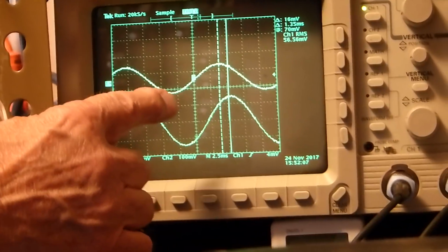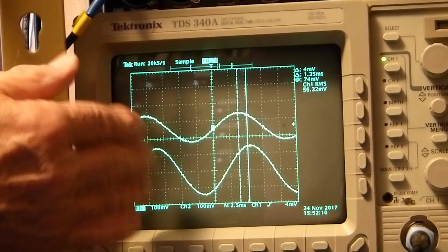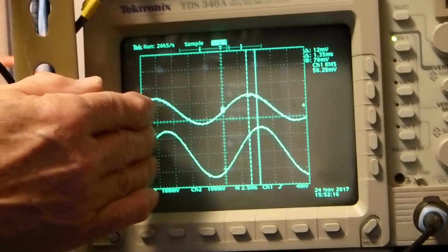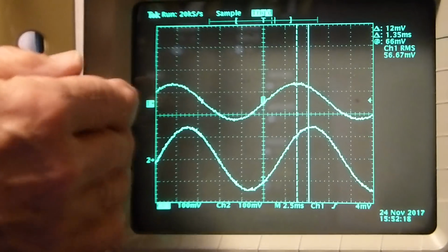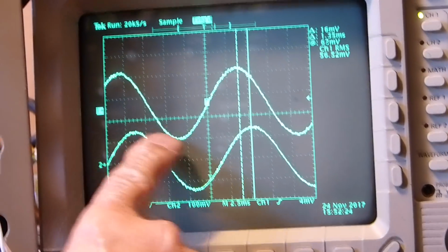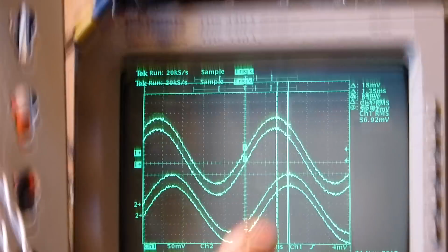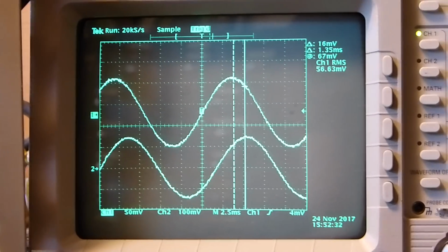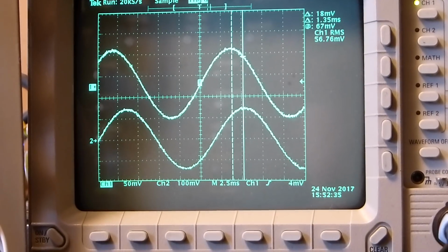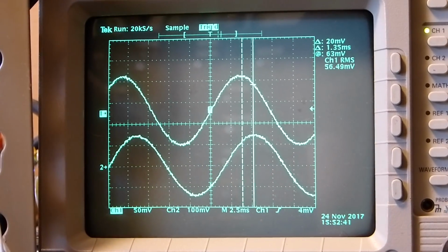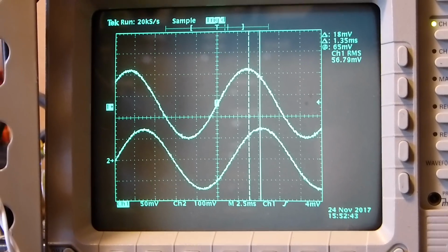Now we got to measure our phase angle again. As you notice, it changed, but the amplitude is about the same. The amplitude is about the same because I changed the resistor to 10K, but I also changed the inductor from 1 Henry to 17.5 Henries. And of course we can multiply this up if this makes things easier. But you see, it's starting to get noisy just a little bit, and it's not all that much. So all of the measurements are somewhere between about 900 microseconds, which is 0.9 milliseconds, up to maybe 2.5 milliseconds. That's what I have found to be the range from measuring down at a 0.5 Henry up to 50 Henries.